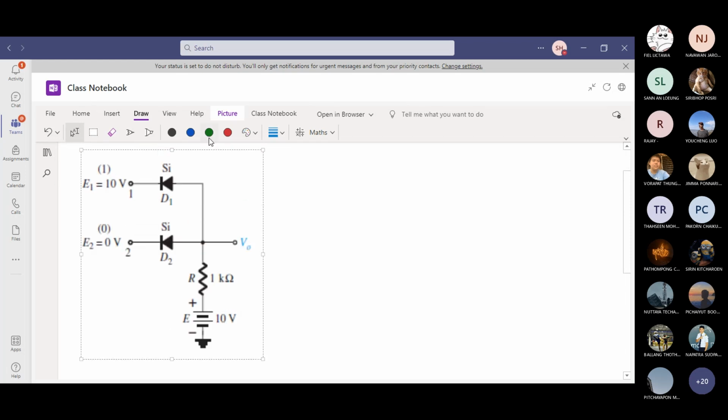The easiest approach for this particular problem is, I see a path established from the bottom, so let me look at the bottom part of the circuit. Look at the voltage that's coming in and look at the orientation of D2. Is it on or off? So D2 polarity is like this, anode, cathode on the left. Do you think it's forward biased?